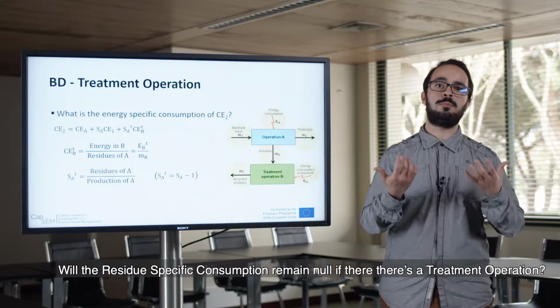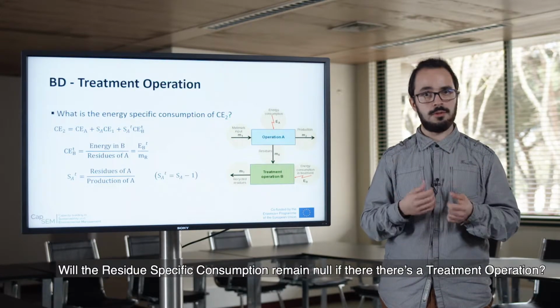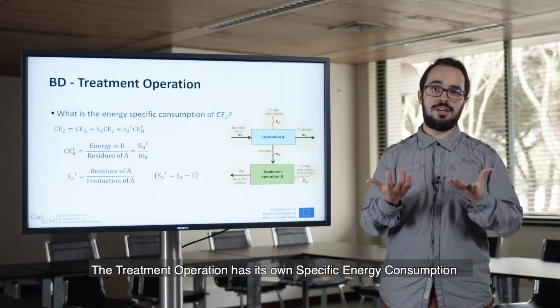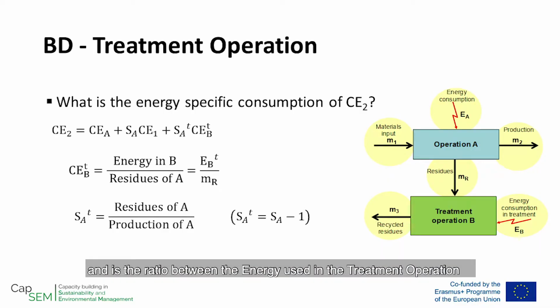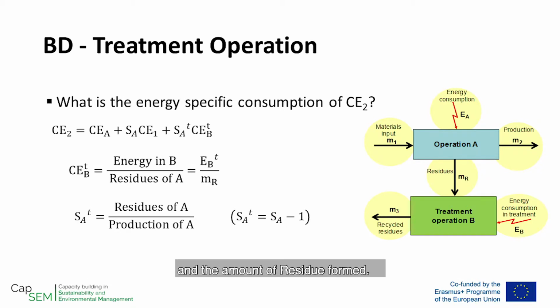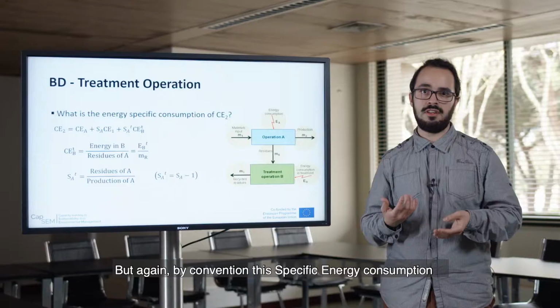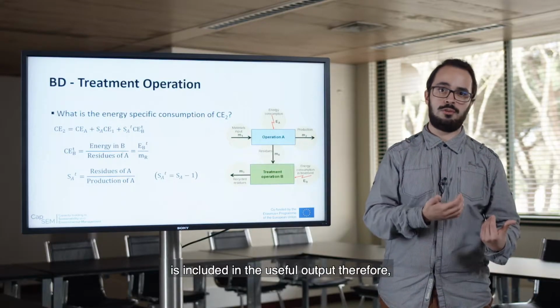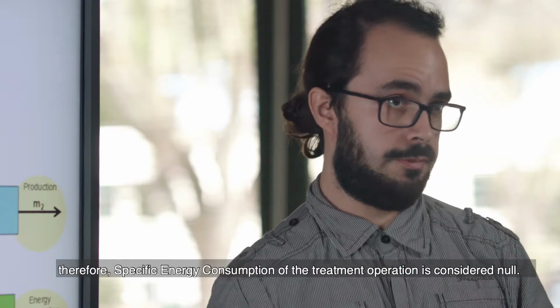Will the residue specific consumption remain null if there is a treatment operation? Well, the treatment operation has its own specific energy consumption, and it's the ratio between the energy used in the treatment operation and the amount of residue formed. But again, by convention, this specific consumption is included in the useful output. Therefore, specific energy consumption of the treatment operation is considered null.